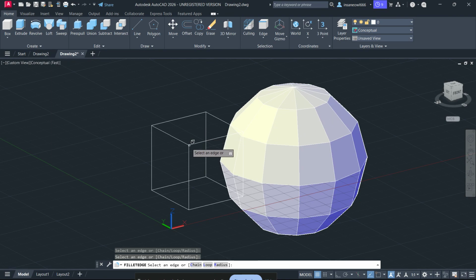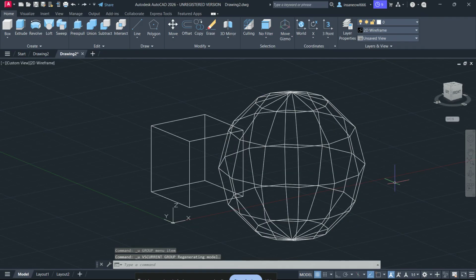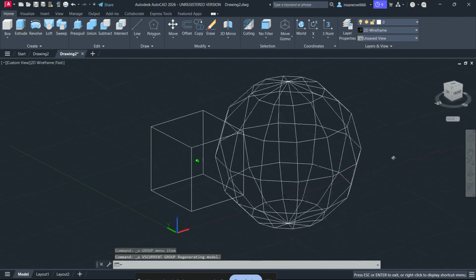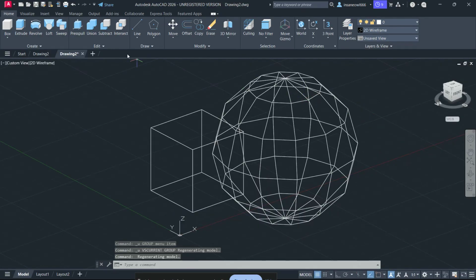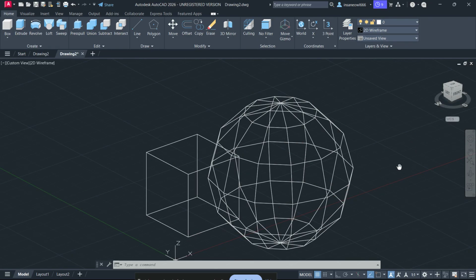The first fix to try is reducing the radius. If you're trying a fillet radius like 10, drop it down to 1 and test it again. If the smaller value works, that usually confirms the original radius was mathematically too large for the available space. In many cases, just lowering the size slightly is enough to make the operation succeed. If your model is small or detailed, this step is especially important.